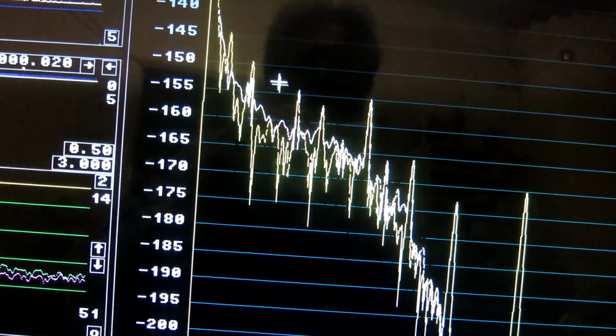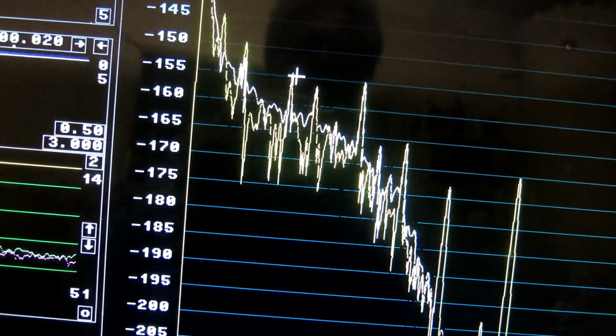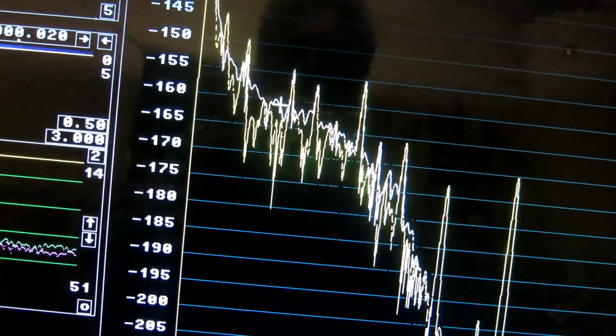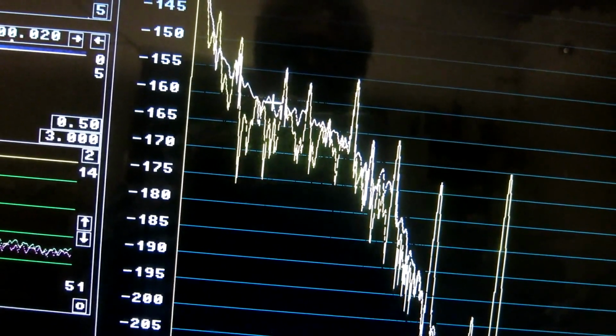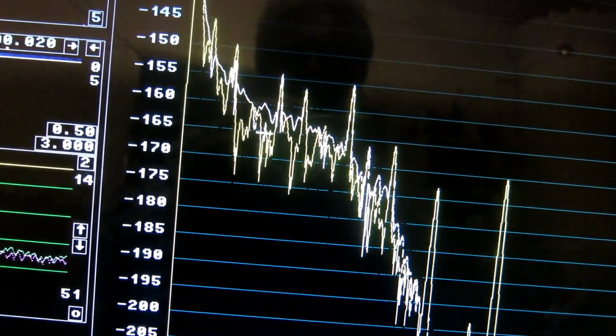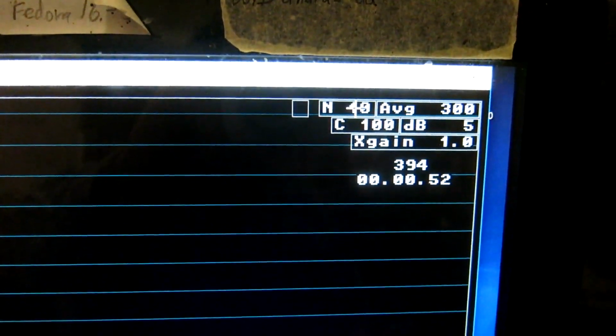But I can see here, here is 200 Hertz, so 150 Hertz. I read minus 161 and 164.5 or so for the phase noise. And of course I can go the other way around, and I put 14 here.